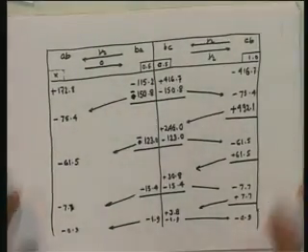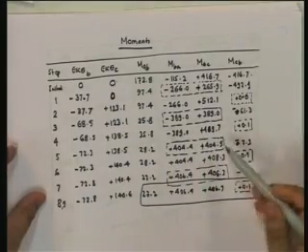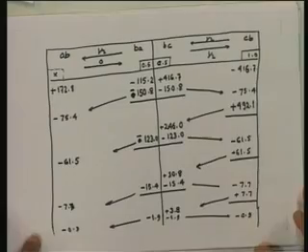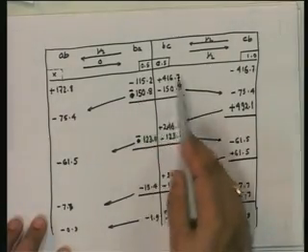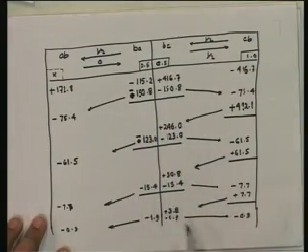The final value you get is what we got here. And at every intermediate step, if you add them up, you will see that you will get this. So actually the moment distribution method mimics this. The only thing is that in the moment distribution method, all we are doing is computing unbalanced moments, distributing it, carrying it over, distributing it, carrying it over, distributing it, carrying it over. Okay? So the physics behind the moment distribution method is, what you are doing is initially clamped.